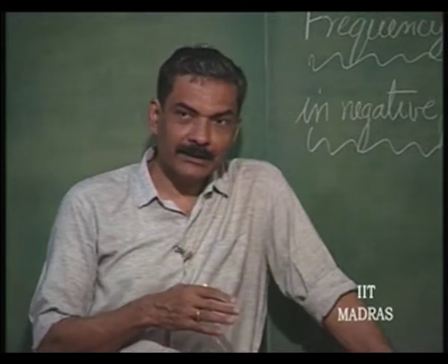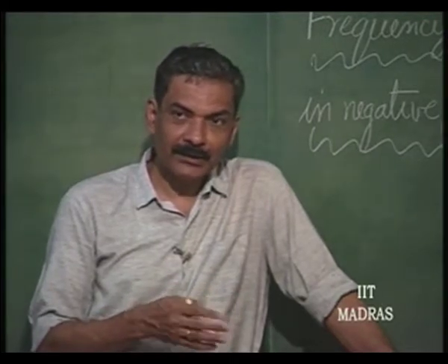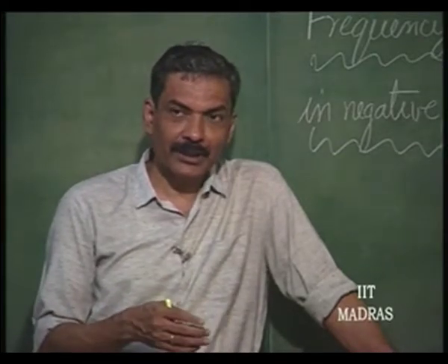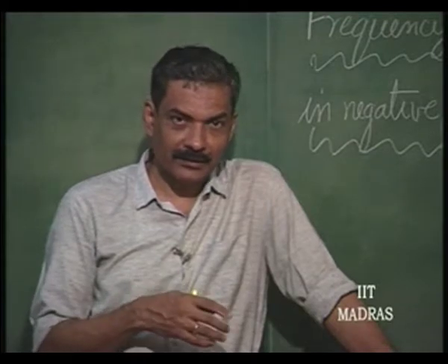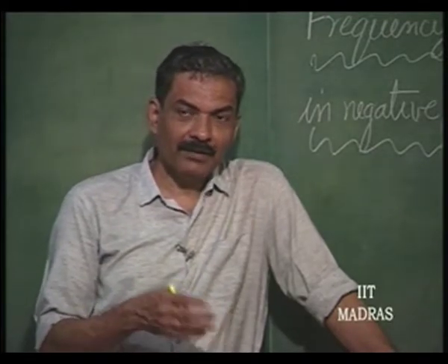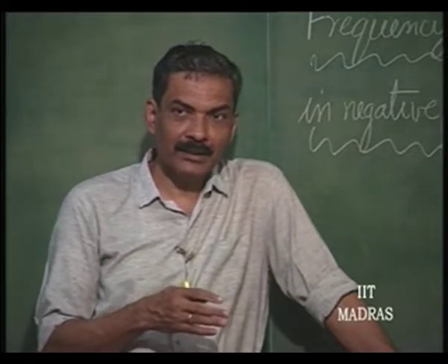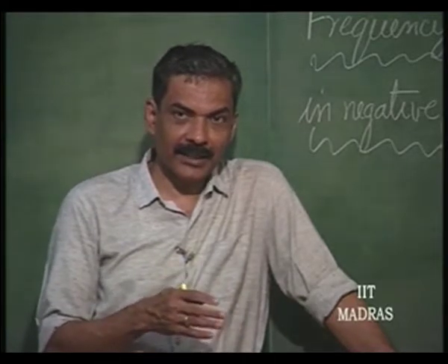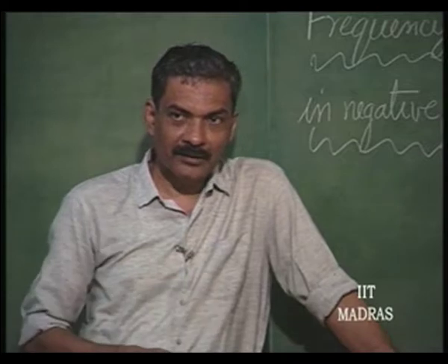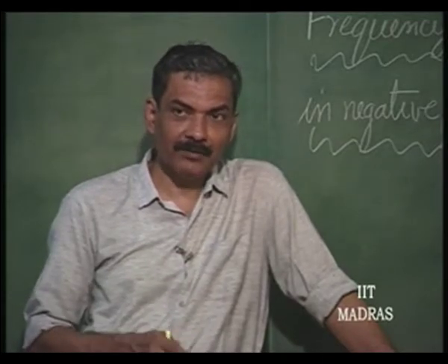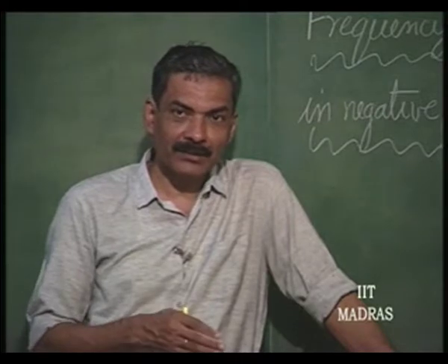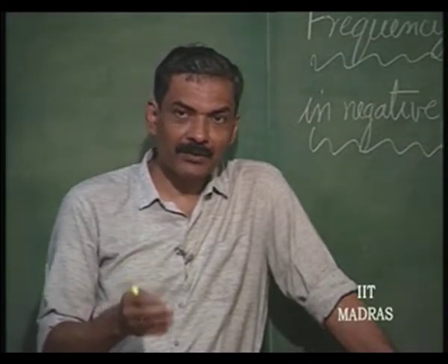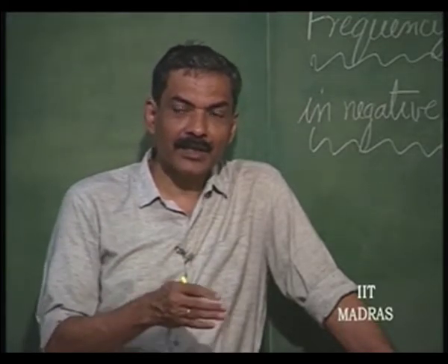Further, we discussed making a sinusoidal oscillator by simulating a second order differential equation, or making the poles get located on the imaginary axis. In all our filter functions, the poles must necessarily be located on the left half of the S plane. In the case of an oscillator, they can lie on the j omega axis, or preferably, to make it build up oscillation, we purposely locate them on the right half of the S plane and then bring them over to the imaginary axis slowly at the required amplitude of oscillation.